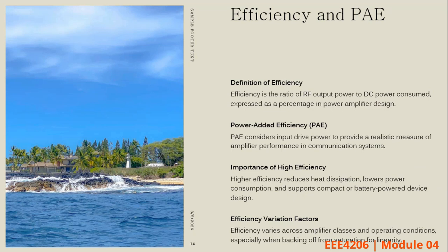So in real systems, we also consider what we call the PAE, or power added efficiency. And this accounts for the input drive power as well. So there is the input drive power that is provided, and that provides a realistic measure of amplifier performance in communication systems. You will also see in the notes I provided the formulas for computing the efficiency and the PAE, and also examples. So you look at them critically, understand and practice.